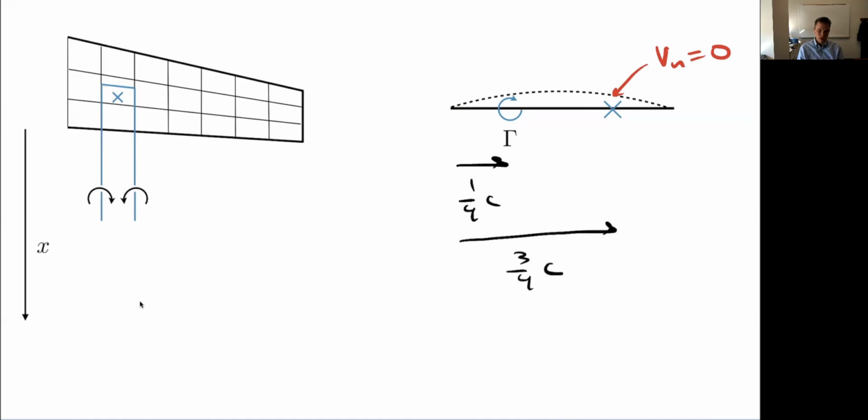Now, when we have chord-wise panels, we build off that idea, and what we do is for each little panel here, we put the bound vortex at the quarter chord of that panel, and we would put the control point at 3/4 chord of just that panel. This is getting a little hard to draw for size, but let me try here. Let's say that this dimension here is S, then we would call this 1/4 S. And then this distance here to where the control point is, that would be 3/4 S.